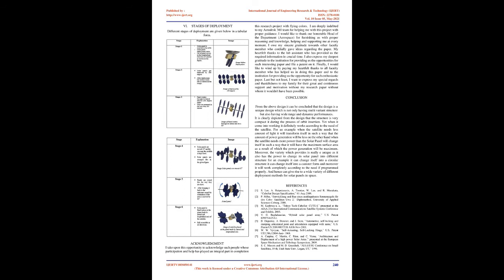Current solar cells provide a conversion efficiency of 28.3% and experience a degradation of 15% by 1 MeV in 33 years. Triple junction solar cells offer the highest conversion rate and a good radiation resistance. This enables this project of reaching the optimum power output from the solar cells. Therefore, triple junction solar cells will be used within this paper. Each panel contains 6 solar cells of 12V. Hexagonal shape is given to fit the 6 panels altogether, apt for the design.